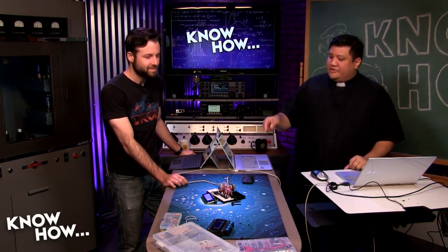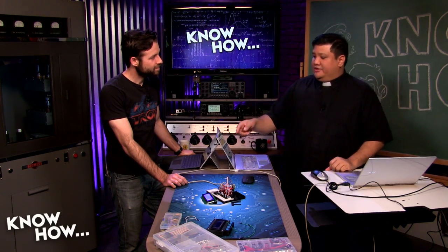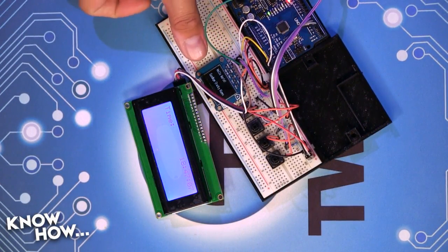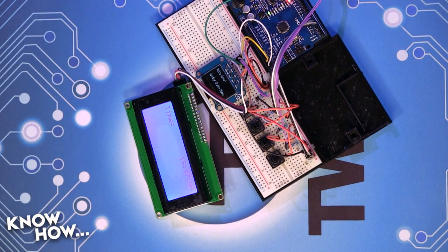Yeah. And actually, since I've got an RTC in this already, since I want to make this blink every second, rather than saying delay a second, I would just say, if the second equals even, show it. If the second equals odd, clear it. Okay. And it would just go back and forth, back and forth.